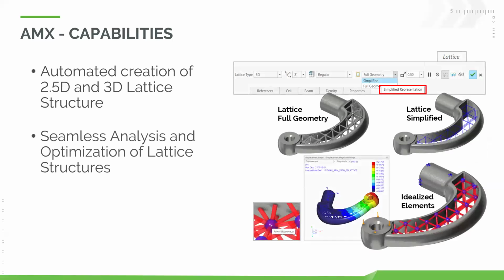After you've created the lattice, maybe you want to try out some different ones, go ahead and actually use Creo's analysis capabilities to find the best possible lattice. You can integrate this with Creo's different simulation tools. So not just throw a lattice in there just to do it, but actually try different ones out, figure out what the best design option is, explore it, and come out with the best solution.